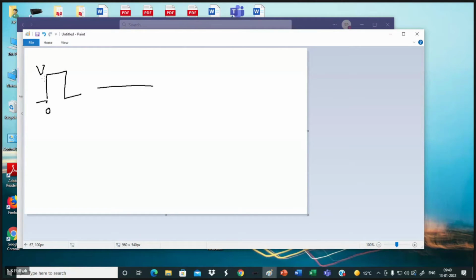Now, this we are putting here. I am putting a resistance here and a capacitor here. This is my signal, and this is the one I am interested in, V naught T, that is going to operate my switch. At what time the switch will be operated, how much delay will be there, that will be very well designed, checking whether it sustains that particular clock frequency or not.